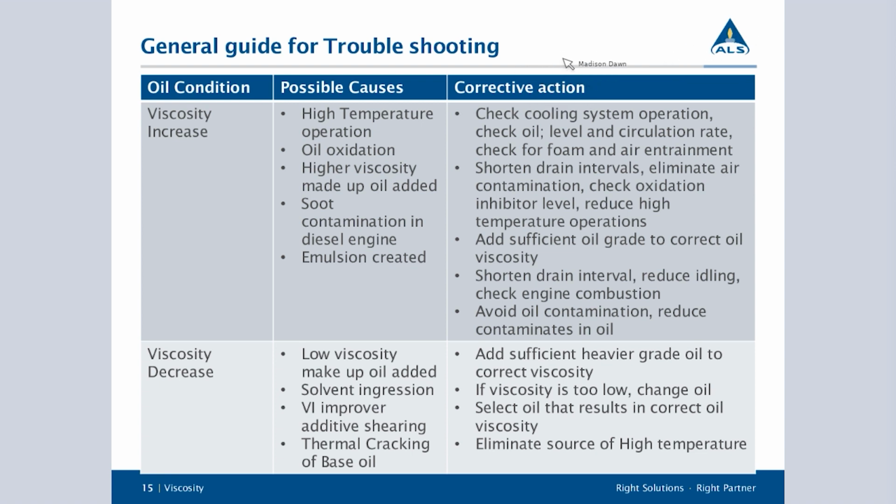And so you start to see that you have thinner oil, meaning that you might need to look at a different oil for your system so that it can withstand the temperatures that it's operating at, as well as looking at eliminating the sources of those high temperatures, whether that's contamination or maybe an issue that's occurring.